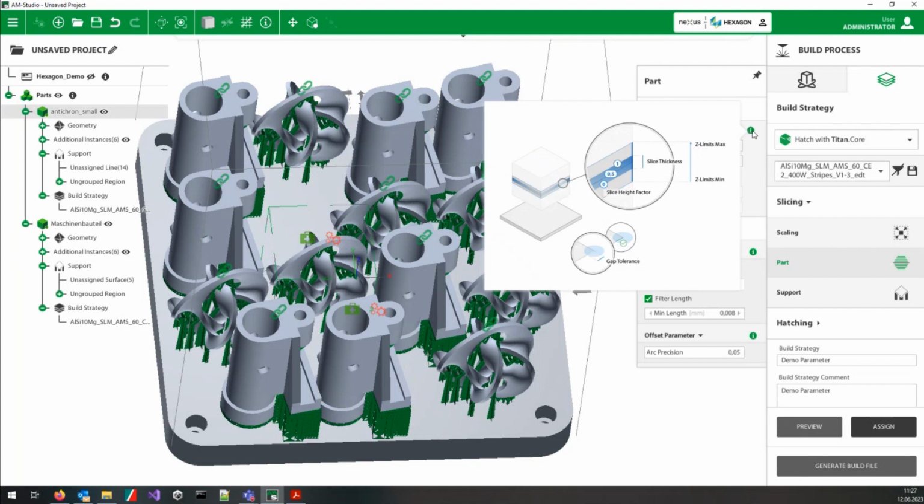I think EOS is working differently. That's the set position where the laser focuses when energizing the layer. Okay, clear. So most of the time it is in the middle? Yeah, 0.5 is the middle, it's the standard.